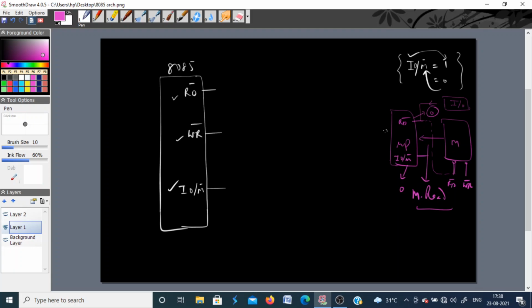So to avoid this confusion, if this signal is 0 and read is 0, you can say, okay, definitely it is a memory read operation. So you can combine these 2 signals using a logic circuit, a very simple OR gate. If you use a simple OR gate, this will give a signal which is used for memory read only. Active low signal, of course, because this is an OR gate.